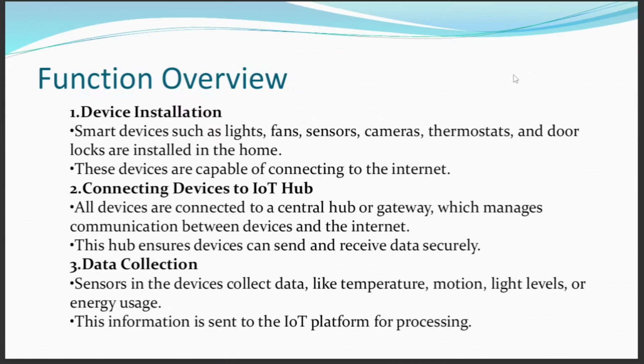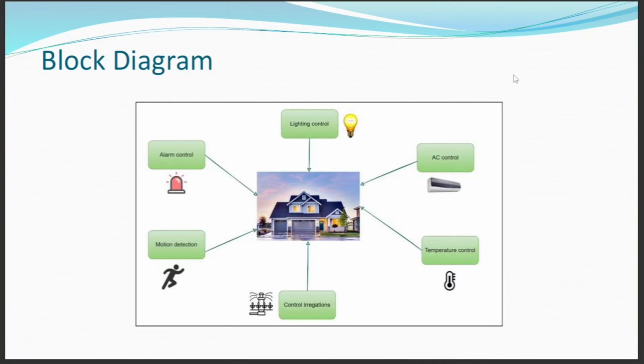smoke detection. Coming to block diagram explanation, this block diagram shows the relation between the main parts of our project. The Arduino UNO is the central controller that reads the input from the sensors and drives output to the actuators. The LDR and LM35 sensors are connected to analog pins of the Arduino to provide real-time light intensity and temperature readings. An Ethernet shield attached to the Arduino provides network connectivity so the system can be controlled remotely through the internet.